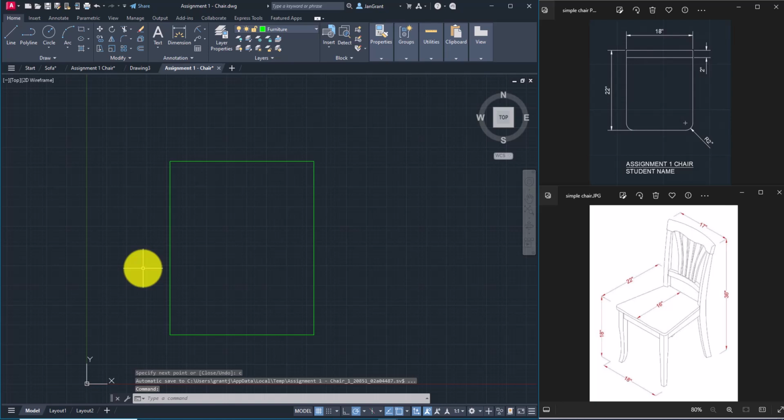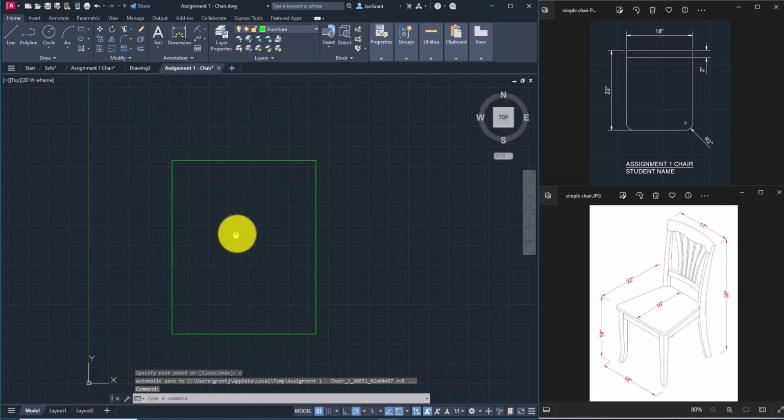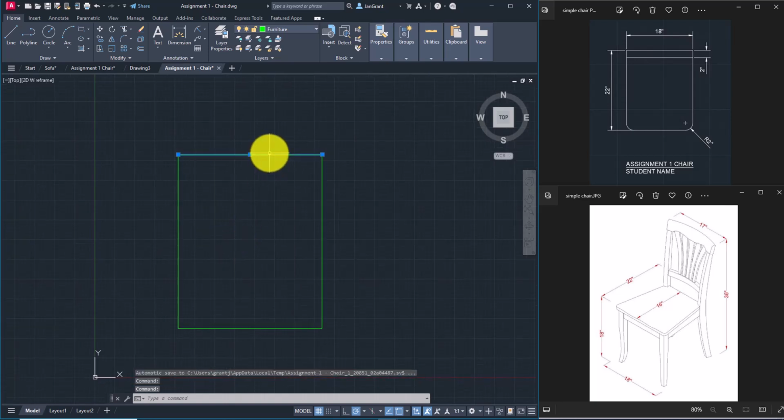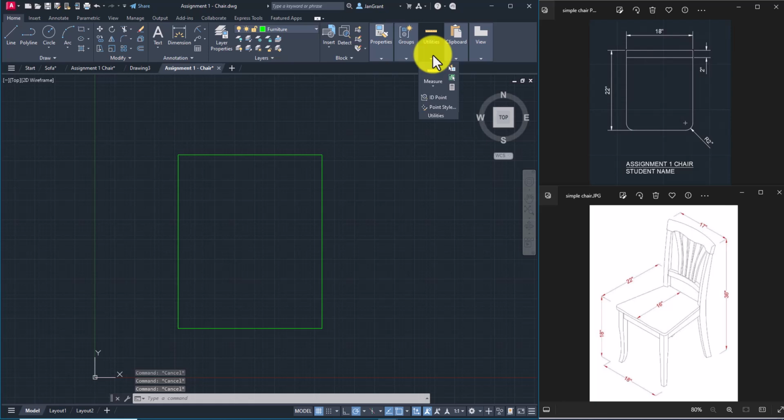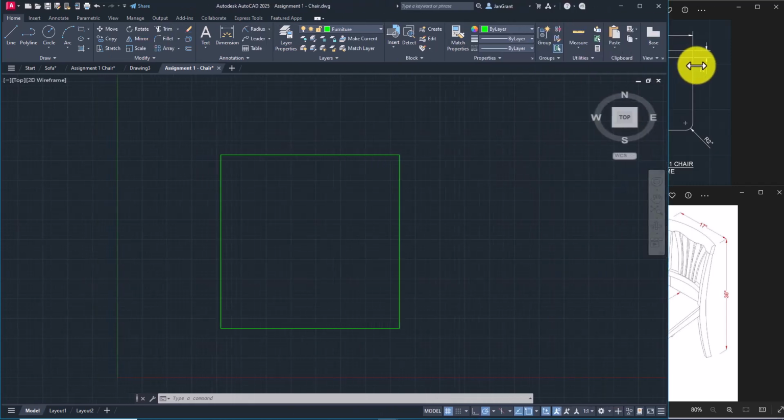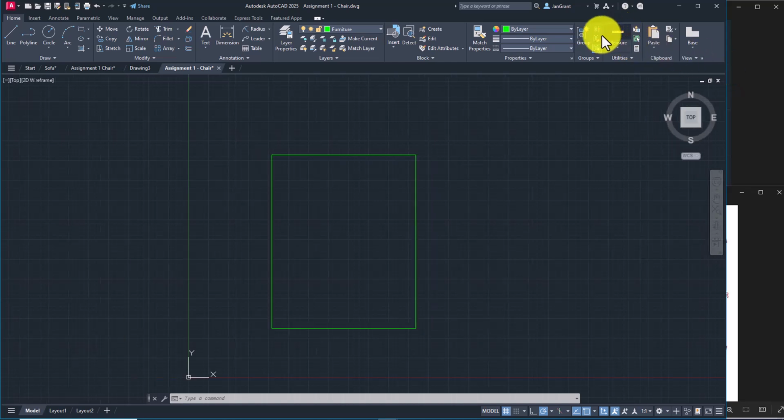Now, we said you could double click on the line to see that that's 18. I'm going to use my escape key to get out of that. There is another measurement tool up here. It's under utilities, the utilities panel. If I made this bigger all the way across, you'd see the utilities panel with measure right here.